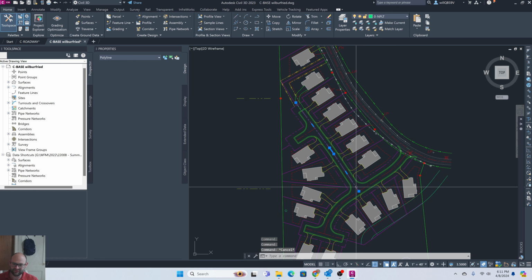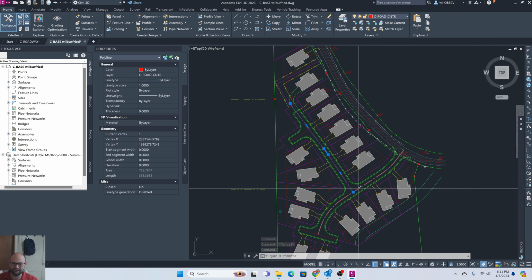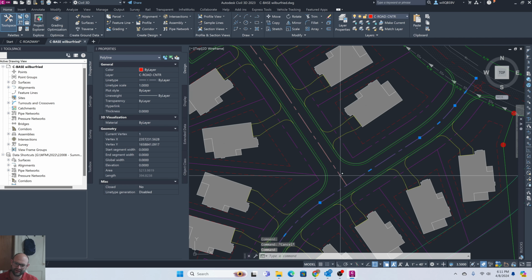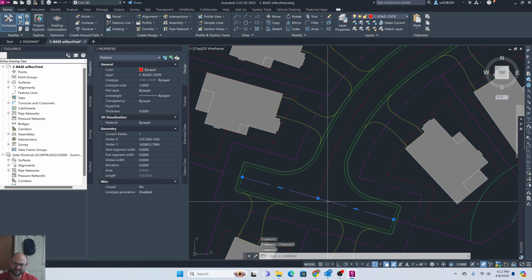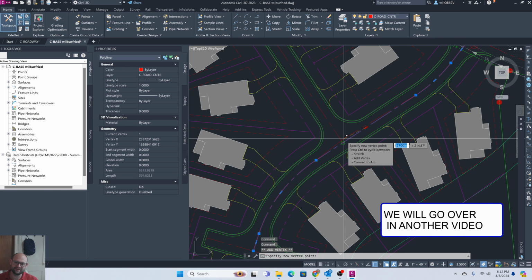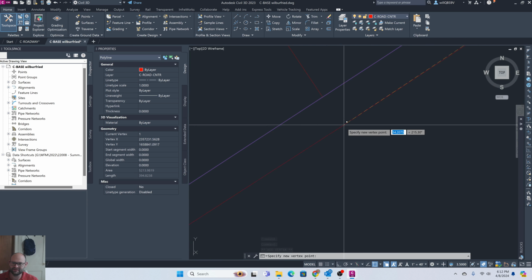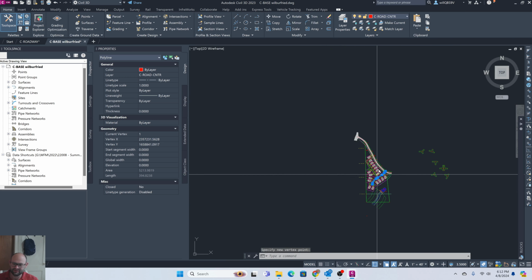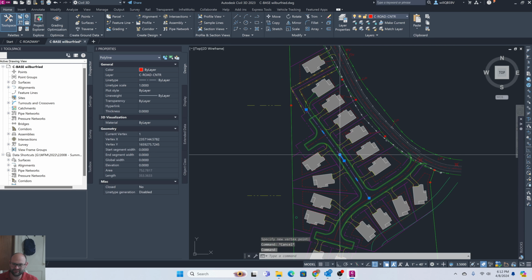I'm going to run through and do some of my typical checks before I use these lines in the other file. One thing I like to do is go ahead and add vertexes at all of the intersecting points. Just makes it easier to see the intersections once you create a profile view for them. So I'll add vertex here, snag it to that endpoint, make sure it's where it needs to be first. Click it in there, cool. This is also a straightaway. I can check that by hovering over the grip.